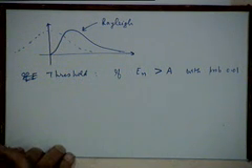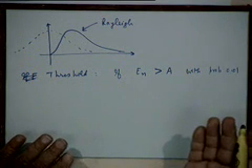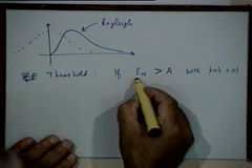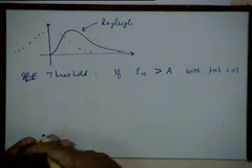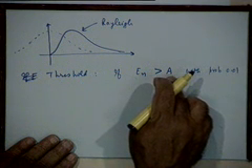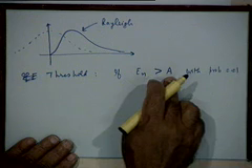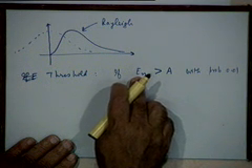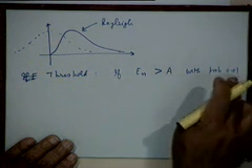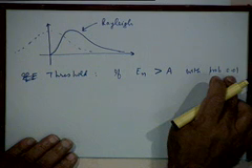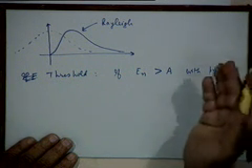Basically, we would like this noise to be much smaller. When the noise is much smaller, the probability of this exceeding the carrier would be very small, right. What we are saying is, if the probability of the noise amplitude exceeding the carrier amplitude becomes 0.01, that is the point at which we will say the threshold has started.